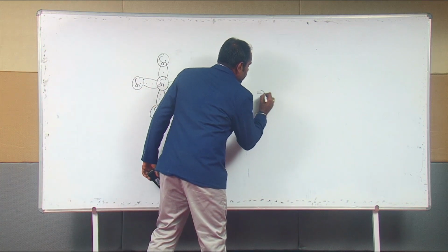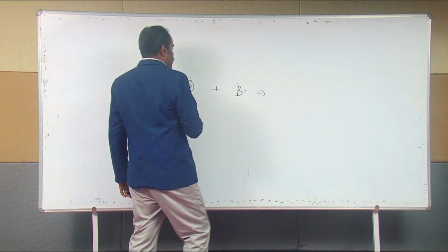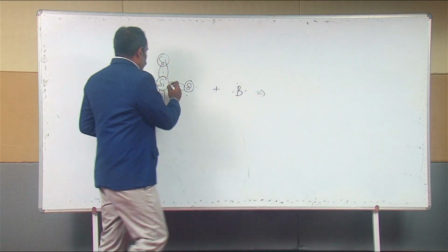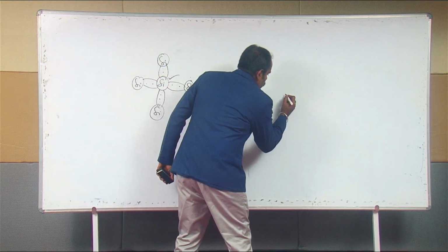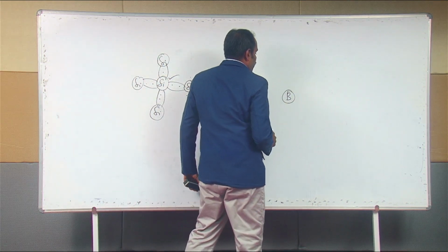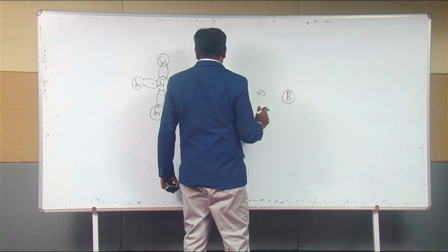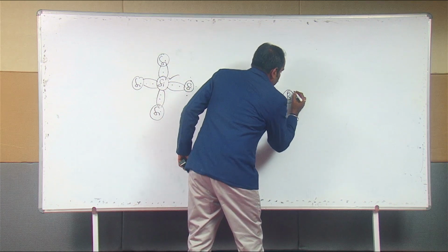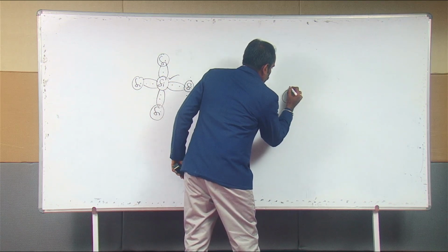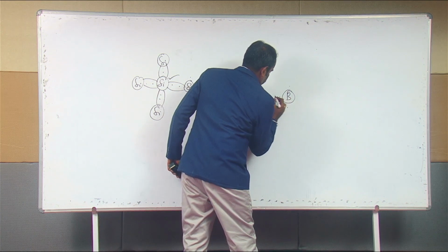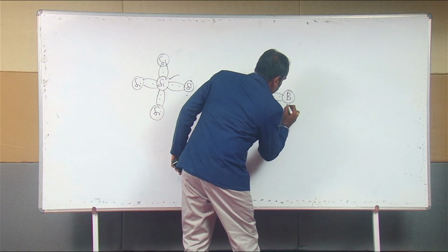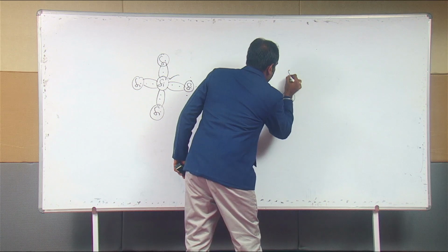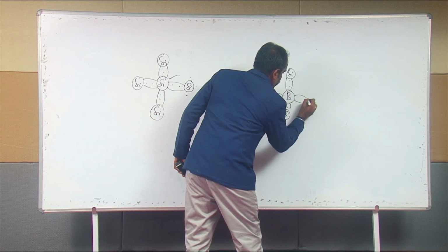And once you add the boron impurity atom into the intrinsic semiconductor, one of the silicon atoms will get replaced by this boron atom. So one of the parent silicon atoms is getting replaced by the boron atom, and the 3 valence electrons belonging to this boron atom will be involved in the formation of covalent bonds with the 3 neighboring silicon atoms.